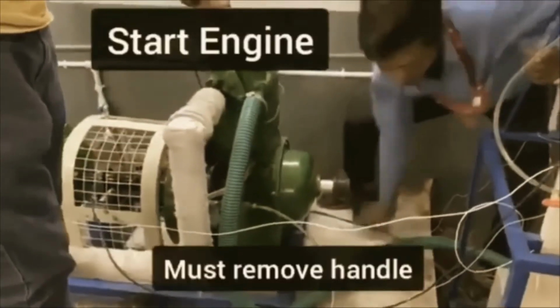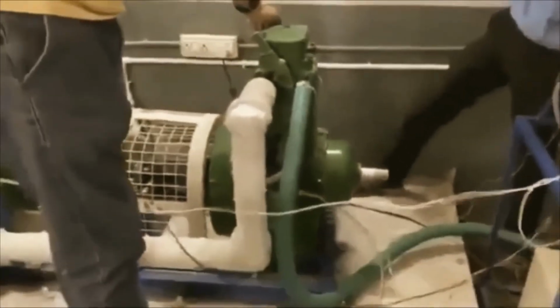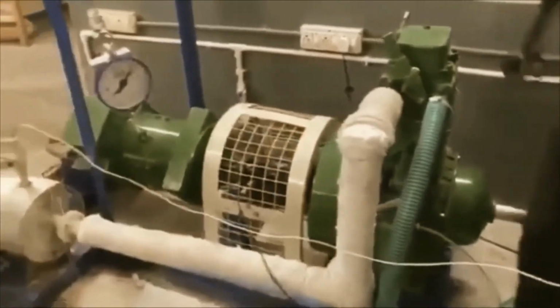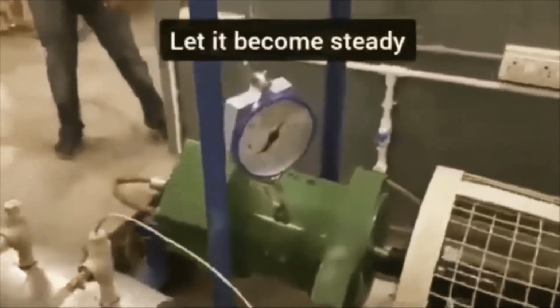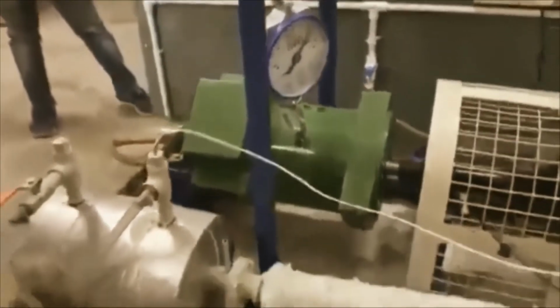How to take readings? First, start the engine. Here the handle must be removed for safety purposes. Here we wait for the RPM to stabilize before starting the experiment. Here some load is applied.